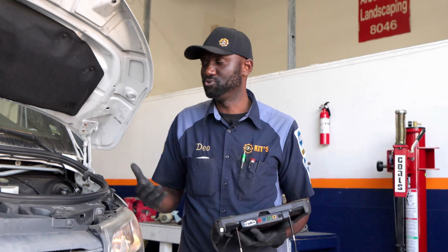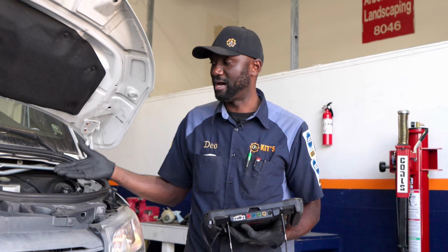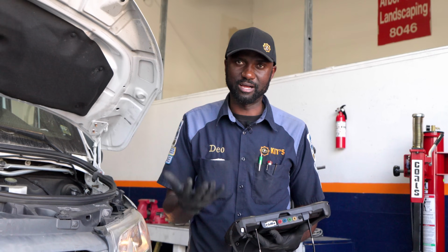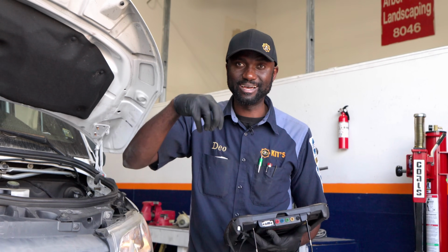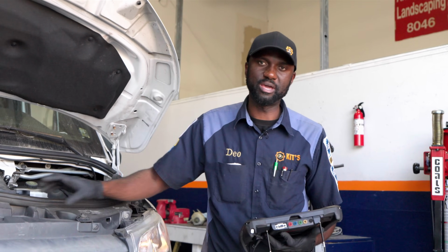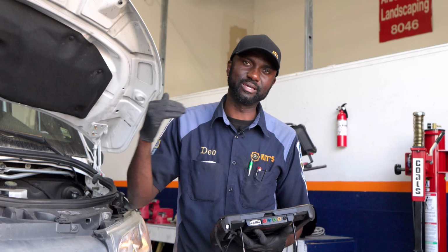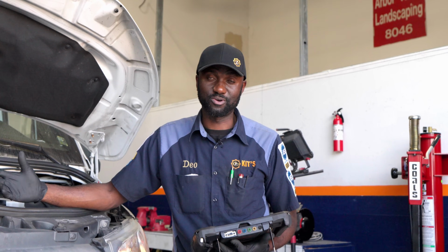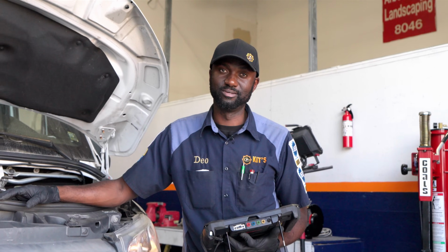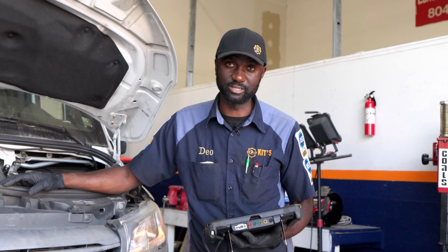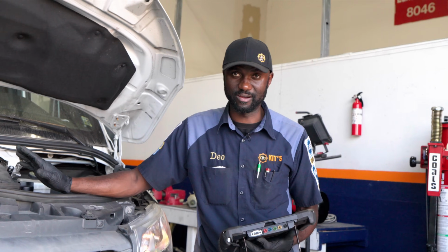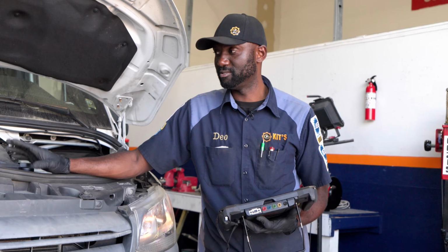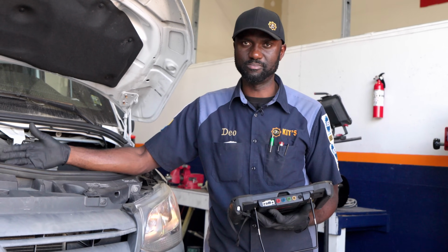Now, the thing is, you can't really test that wiring from outside, because the wiring is actually under the engine, inside the oil pan. So we have to remove the oil pan so we can get access to it. It's a very small component, but it's hard to get to, and it's very costly to do. I've done a couple in the past in SUVs and sedans, so it's basically the same concept here.